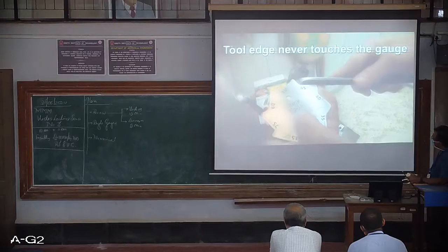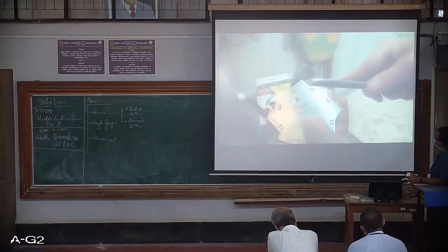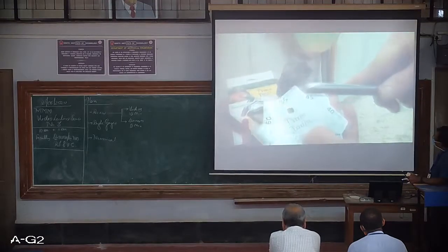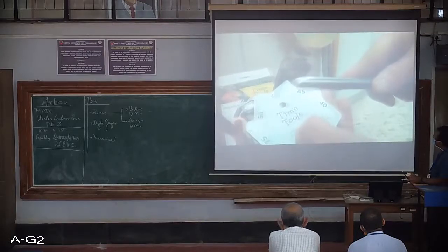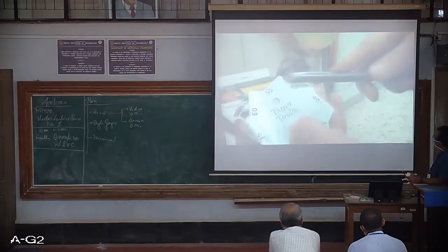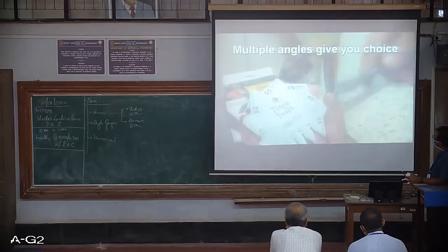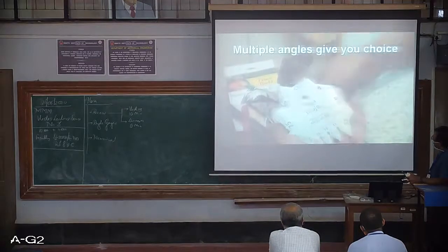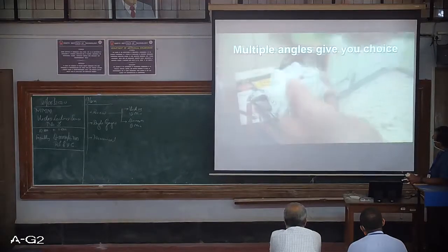So what I do with this is you lay it on top and you just bring it up and you see the edge. There's no light showing through that edge. I know I'm at a perfect 45. So now I can guarantee that everything I do on my grinder is going to match with where I want to be. And the reason I put so many angles on there is because it's different strokes for different folks.